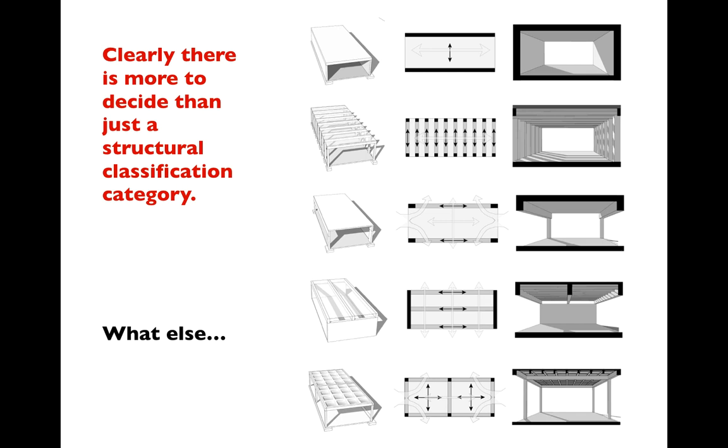So a factory maybe where we have large scale equipment, but we need to put it on 2 or 3 different floors. We might be looking instead at what we call one-way systems. So we might have shear walls or bearing walls on the outside, as you see on the top. We might have relatively thick slabs or relatively deep girders that are spanning in that single direction, right, to accommodate not necessarily a long span high volume, but a span that is bigger than the typical 20 to 30 feet we might get with a slightly less exotic system.